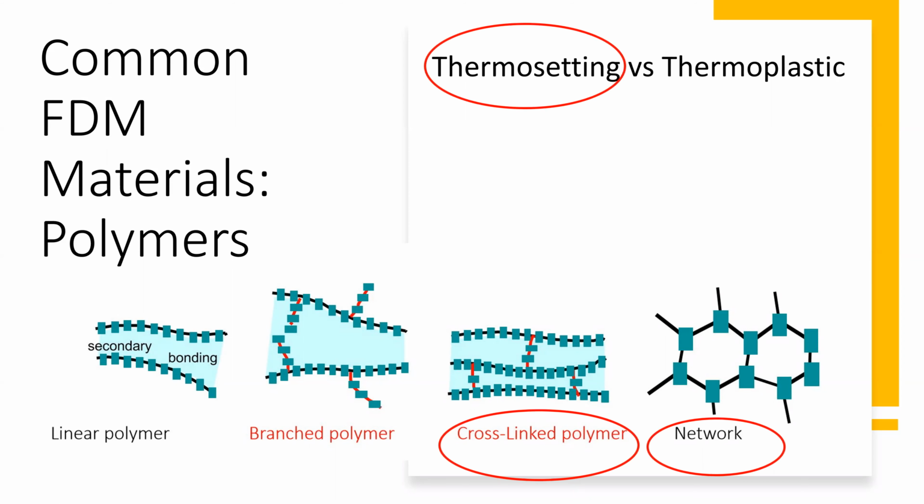Thermosetting polymers are polymers that are not able to be melted again and again. An example of this would be a shampoo bottle. If you were to heat this up, it would simply burn because it has a network polymer structure, which does not allow chains to realign when they have reached glass transition temperature. This can be seen because the bonds in the cross-linked network are covalently bonded, which are much stronger than the van der Waals bonding between these chains.